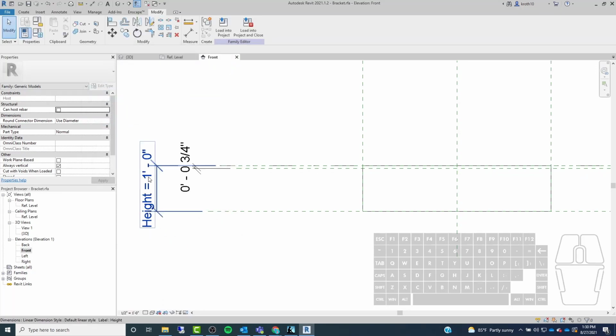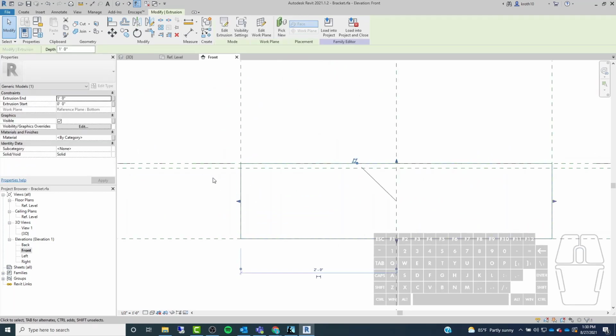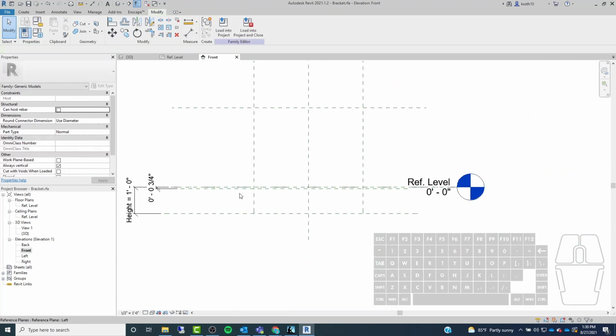And then we're going to click on the extrusion itself right here, and we're going to delete that out. So get rid of that, and then we're going to save the file. Okay. So now we're on to page 21. This is create a new blend. So this is where we're going to add in some new geometry to actually create the bracket shape.